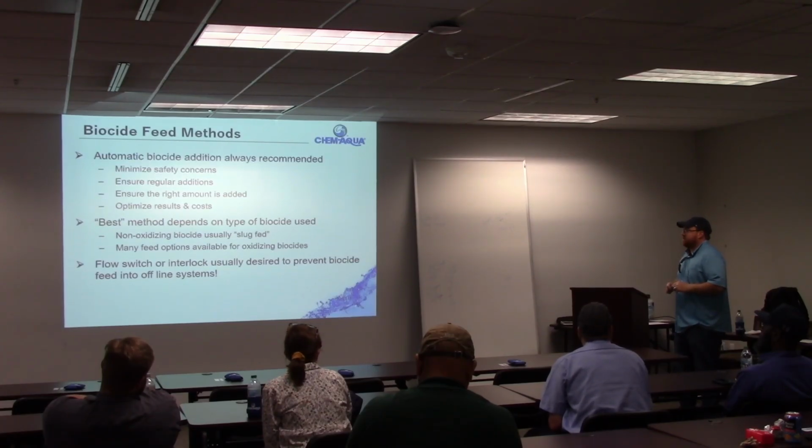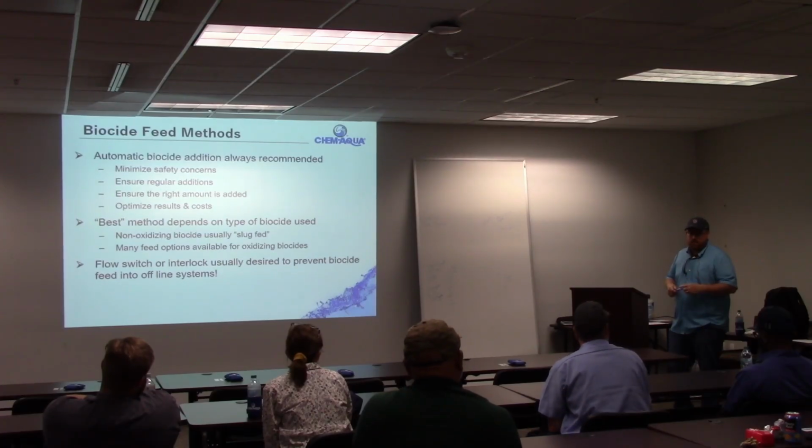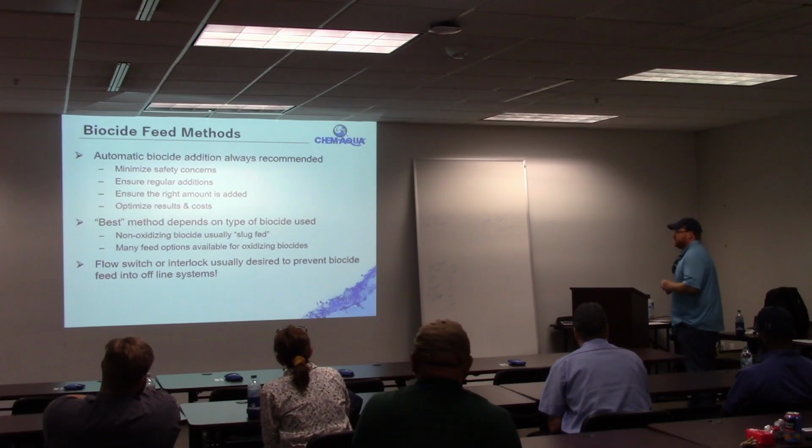So there's other things that come into all that, but generally one of the best ways to make sure that you're feeding the right amount of biocide is to test free chlorine an hour after the feed. If you've got 1 ppm of available chlorine 1 hour after your biocide feed, you're feeding enough biocide.